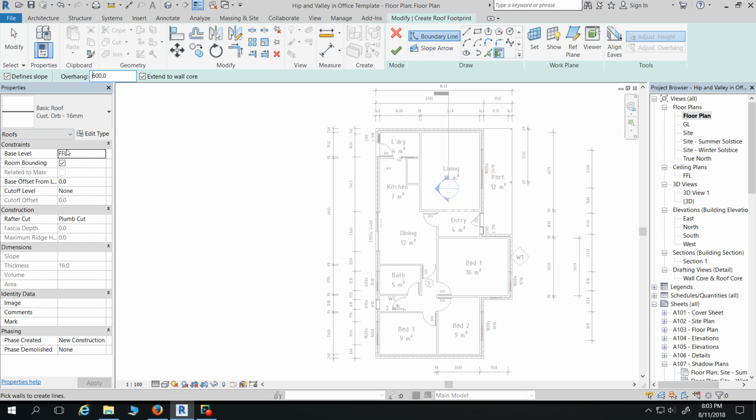And then did it prompt you to choose a level for your ceiling? Yep. And did you guys choose ceiling level? Okay, good. Because sometimes it doesn't prompt me. Like on my project, and at work, on most jobs, it doesn't prompt me to choose a level for the ceiling. So quite often I draw a ceiling on my floor level. How do you change the level? You just select the element and then change the level. So it's easy to fix after the fact, thank God, because I really need to learn to double check what level I'm drawing on. But it's generally not till I go to the 3D and check and go, oh, whoops.